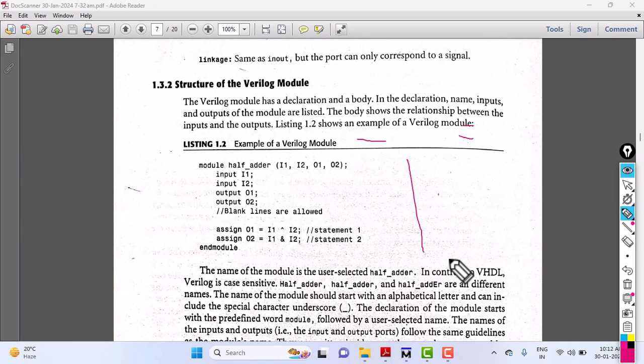You are starting from the top and reaching the bottom level. Bottom level means gate level. If I ask you to design an 8-bit ALU, that's your top level system. And when I say 8-bit ALU, you must also ask me for the complete specifications of this. One important thing, the industry people normally ask you to write down the specifications. If I simply say design an 8-bit ALU, don't blindly go and design it. You must ask me how many operations my ALU should do.